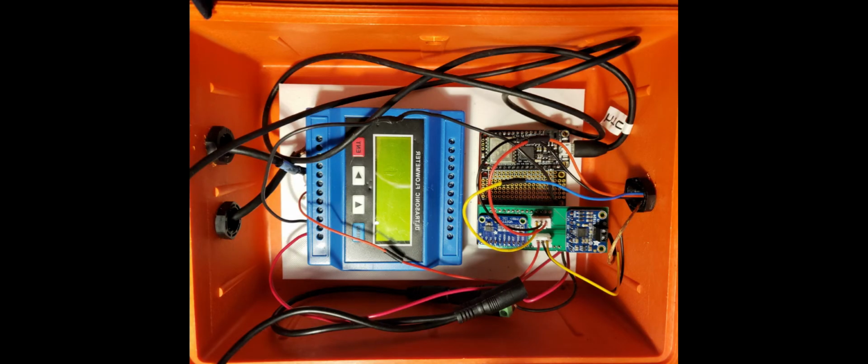This is the bottom of the pelican case, which holds the ultrasonic flow meter on the left and the microcomputing group on the right. The transducer connections enter in from the left into the ultrasonic flow meter controller, and the turbidity and the thermocouple connections enter in from the right. The microcomputing group contains a Feather M0, an Openlogger Hypnos board, and a specialized PCB created to hold all sensor components and convert signals to the proper voltage when necessary.